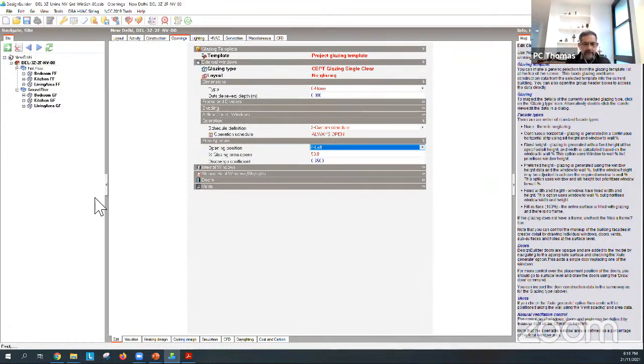Okay, so what have I done? I've told EnergyPlus, switch on the natural ventilation calculations. I've said in the window schedule, I want it to be always open. Okay, so now what I'm going to do is I'm going to run that building.